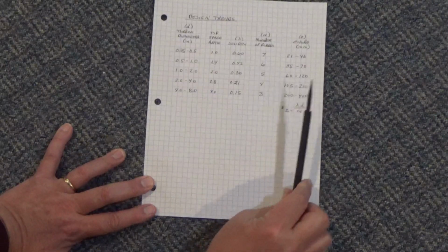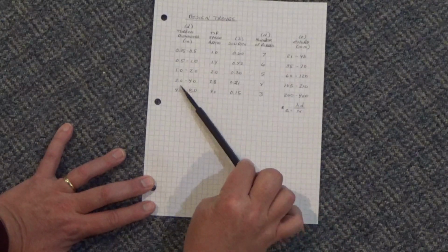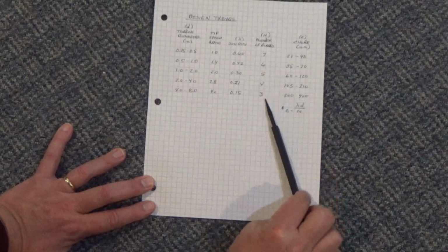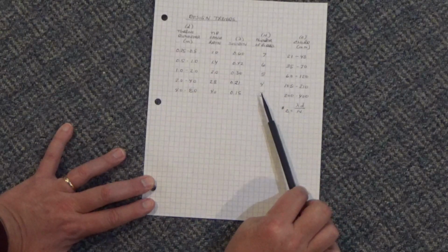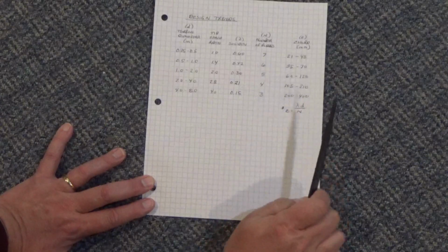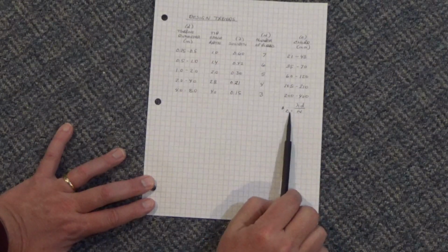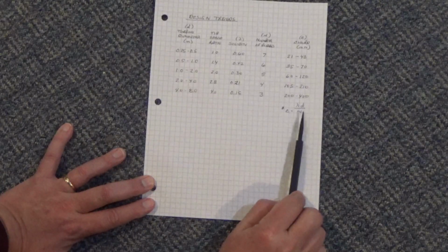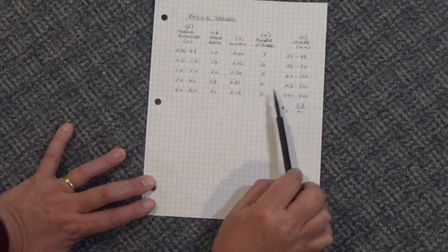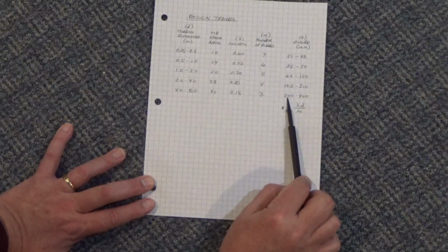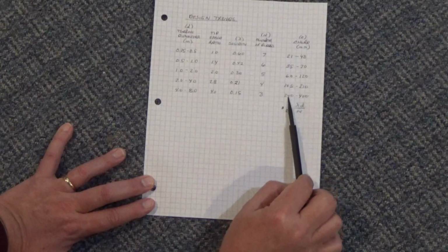So we'd like the chord to stay in those same ratios. And so I looked at different numbers of blades: 3 blades, 4 blades, 5 blades, 6 blades, 7 blades. If you figure the chord being this solidity times the diameter divided by number of blades, if we pick these numbers of blades, then these chords go down almost by half.